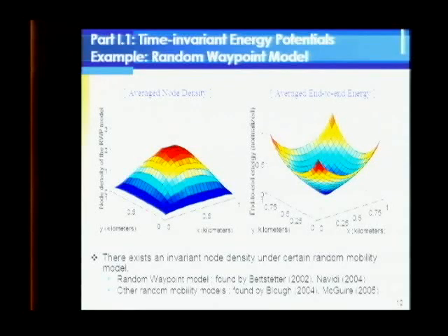Does the shape stay invariant to the density of nodes? If you make the system much less dense or much more dense... If it's much less dense, it would take longer to converge to the same form, but it's invariant to the node density. That's right. Oh, I'm sorry, no, that's not true. The node density function is invariant to the node density, but this is not, because if I double, for example, the number of nodes, the energy consumption, since we're modeling transmit energy, actually goes down. Right, but would the shape be the same? The shape is the same. We simulated this for different numbers of nodes. That's right, but with lower energies, because transmit powers are being scaled.